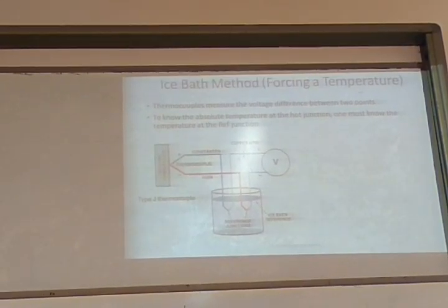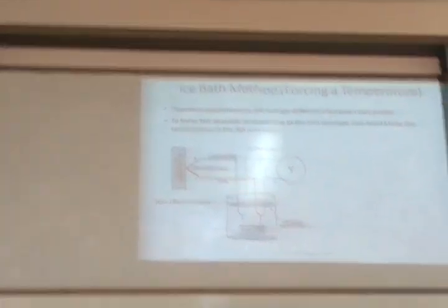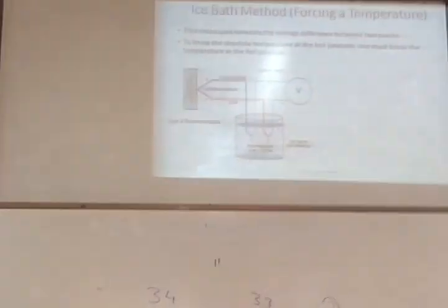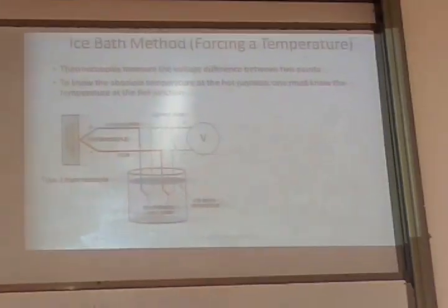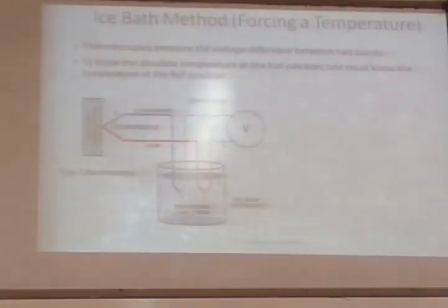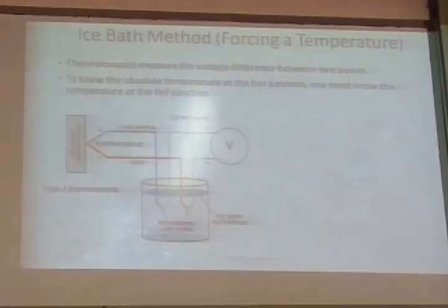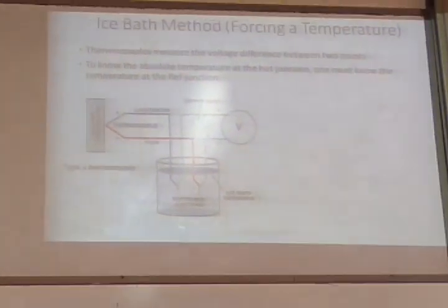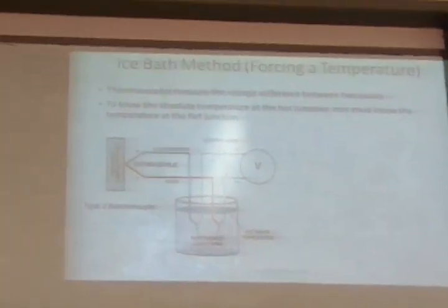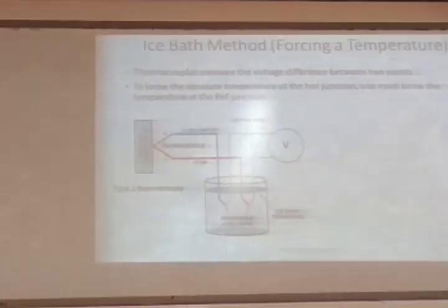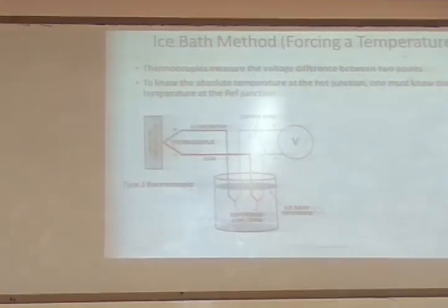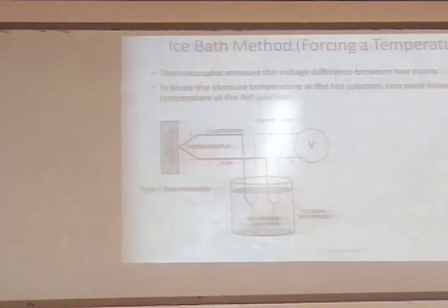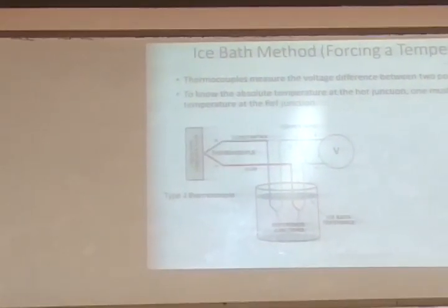While measuring, you will always get some reading. If you build the sensor by yourself, or while measuring, you will know. Some reading will come. Even if you connect a multimeter or oscilloscope, some waveform will come, some reading will come. You don't know whether it is the intended value or it is because of some noise that is picked up. You don't even need to measure. You take a thermocouple and simply keep it near the switch box. Inside the switch box, 230 volts and 55 amps of current are flowing.